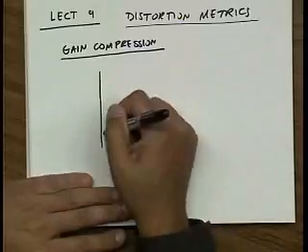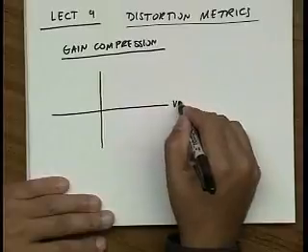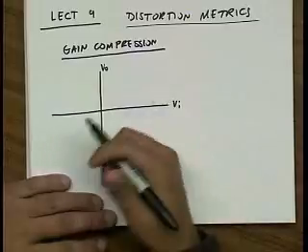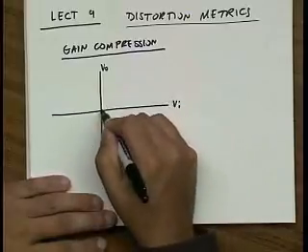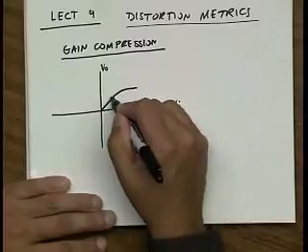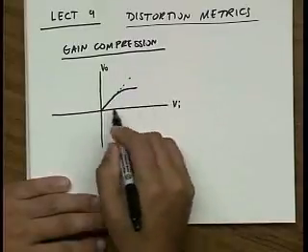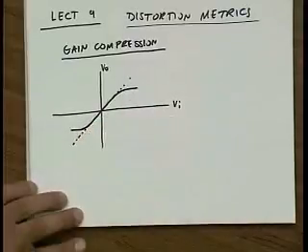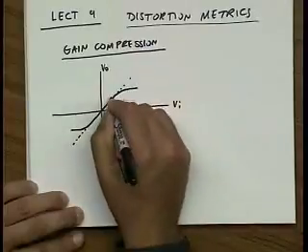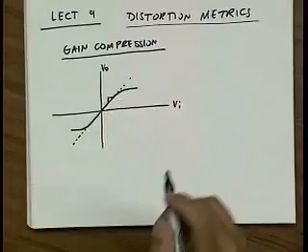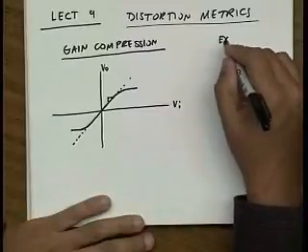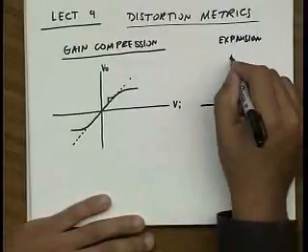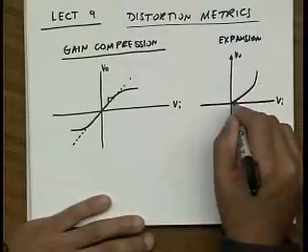Well, first plot the output voltage as a function of the input voltage as you vary the input. So this is the input, this is the output. And this could be an AC signal, it could be a low frequency signal, but what you'll find, as we discussed last lecture, is that this output will eventually compress. And likewise in the negative direction it may do something similar. And so the apparent gain, the gain is proportional to the slope, reduces.